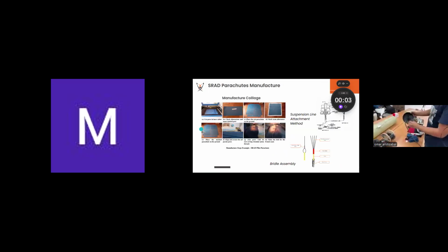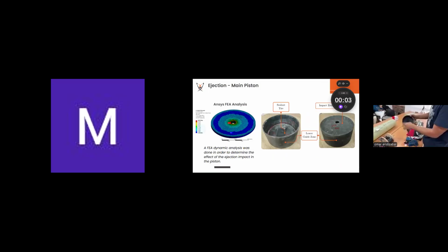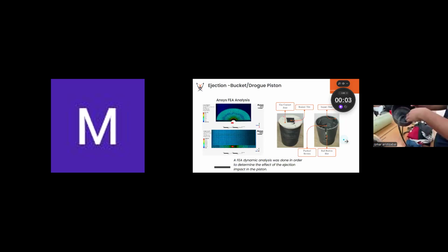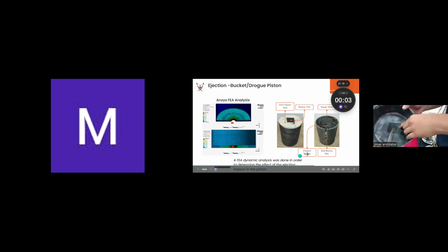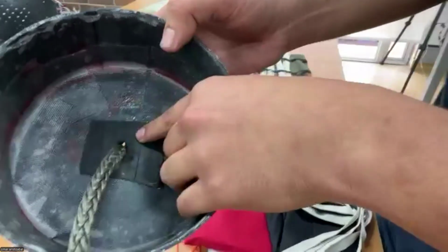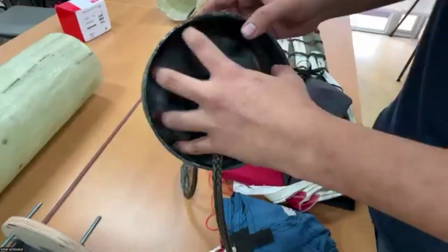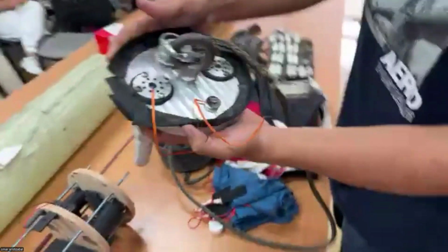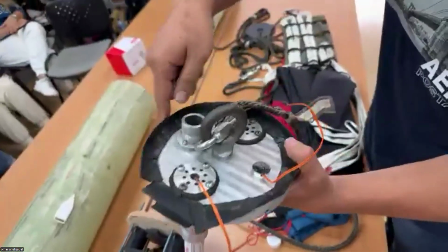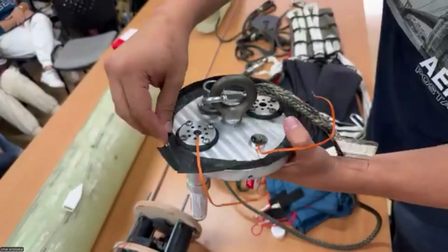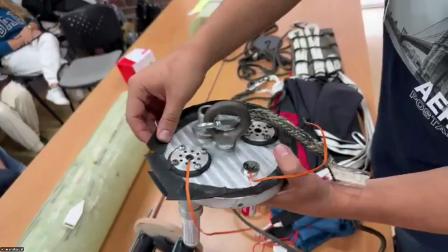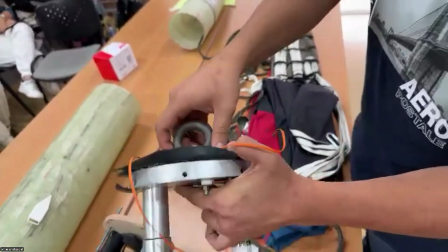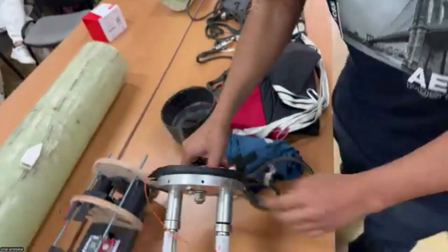These pistons are 3D printed with ASA reinforced with fiberglass on all of the structure. Also, these pistons have a sealant component that is a used tire of a motorbike that we use to seal the ejection gases. This sealant method is also used on the bulkhead of ejections. As you can see, all this pneumatic, all this tire were from a motorbike, and help us to maintain a sealed compartment during the ejection events.